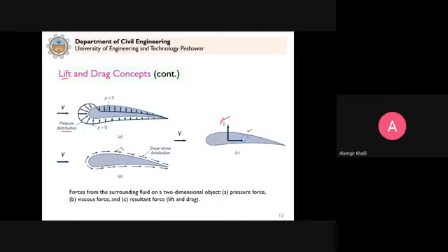So at the underside of this object here, a pressure greater than 0 is developed, but on the top surface of this object the pressure is negative, clear. And you can see here that at the bottom we have a greater pressure and at the top we have smaller pressure. So because of this pressure variation, a force will be generated which will be acting upward, clear, from high pressure to low pressure, and this we call the lift force.